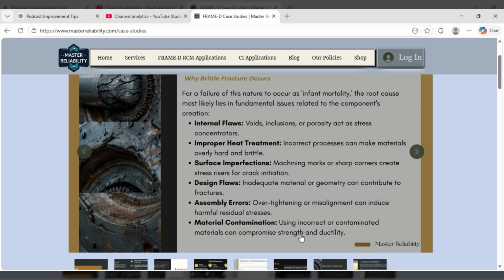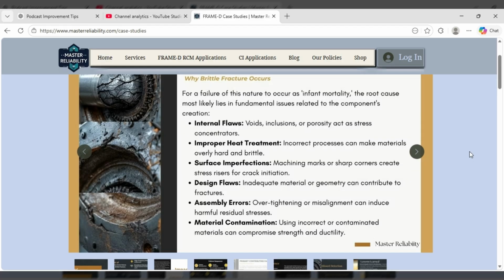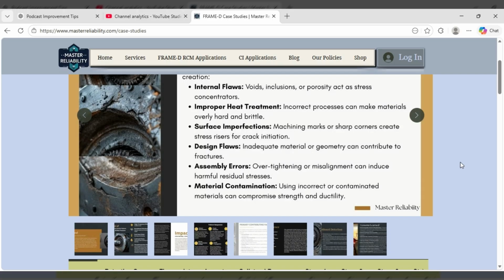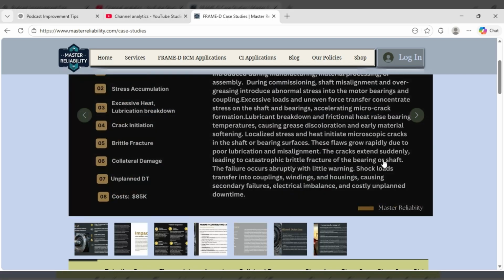And then material contamination, which causes sludge. So let's say it's a case packer and that case packer is around a lot of contamination due to the cardboard. You're going to get that cardboard dust inside bearings where you have your lubrication. That lubrication then causes sludge, and you have this internal mess. So it all adds up.